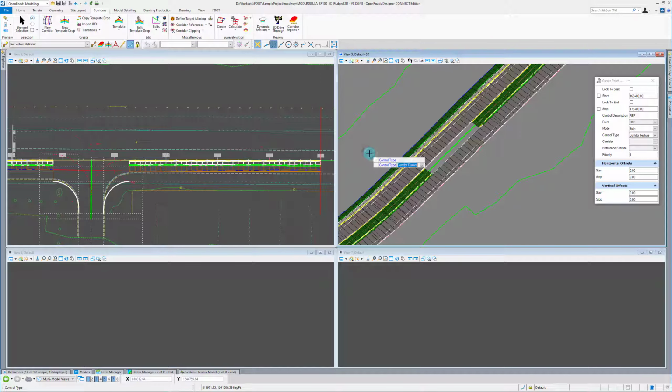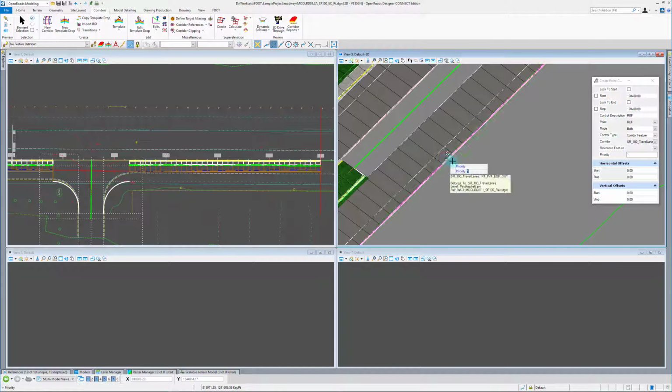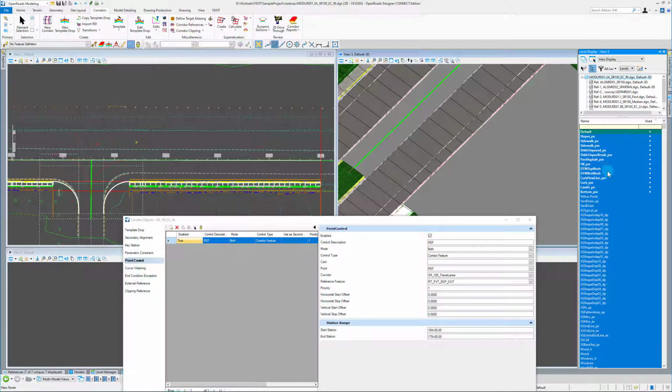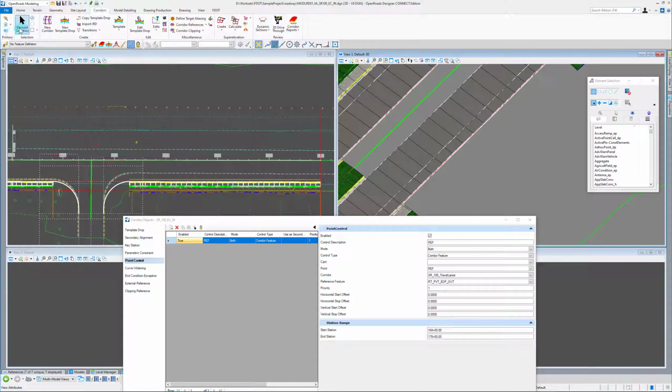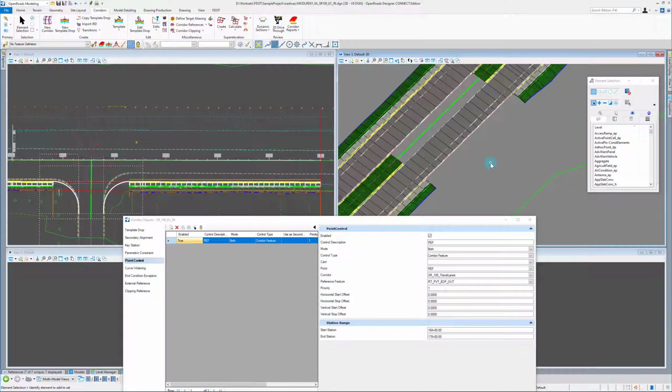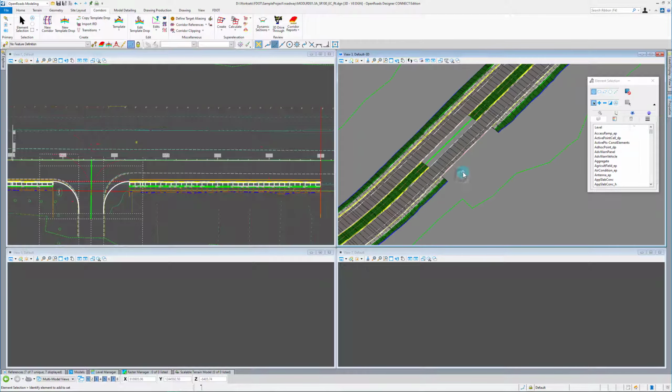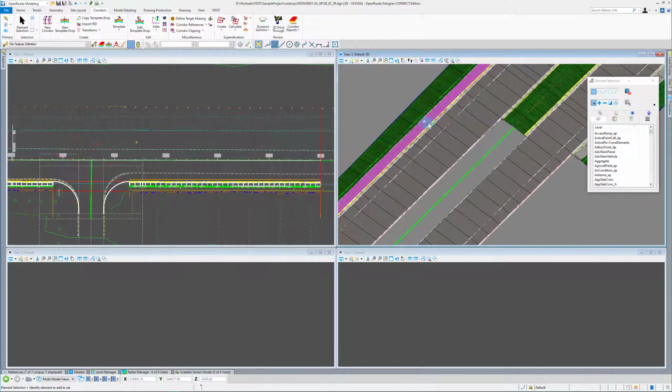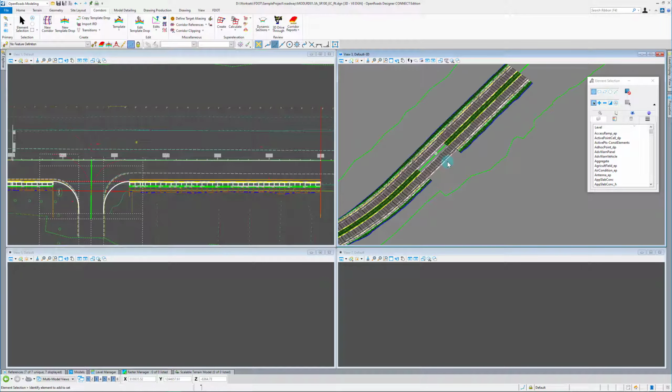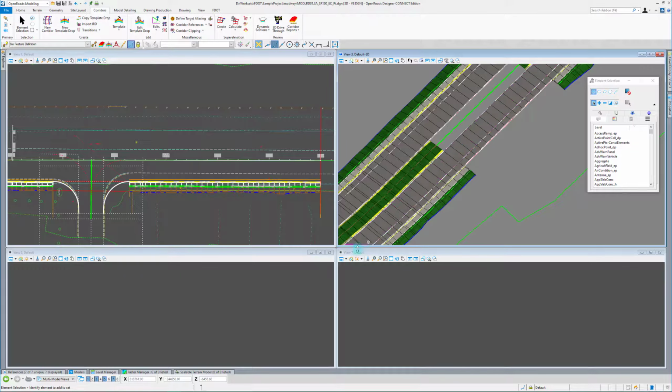So we want to do both. Corridor feature. Easily find my corridor I want to use. And snap to my feature. Click through. Let's turn off our top meshes. So I know it's kind of obnoxious to have that DTM top and bottom mesh, but it's really easy to turn off, and I think once we get down to our 3D deliverables, that's going to be amazingly helpful in creating those 3D deliverables. So I would really stress trying to draw those in all your templates.